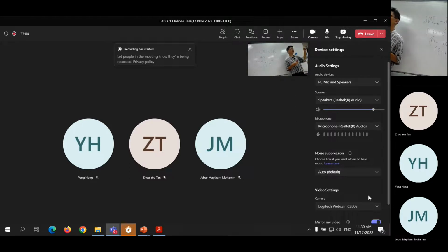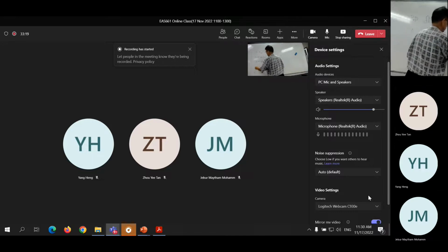which means the equilibrium equations. External force equal to internal force. So by applying principle of virtual displacement, you get equilibrium equations. And from here, you can solve for delta. So here, delta is equal to P over K.